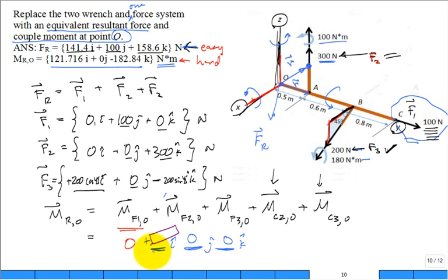Perpendicular distance of a half times the magnitude. A half a meter is that perpendicular distance, times the magnitude of 300 Newton. You get 150 Newton meter, positive. And really, we did a kind of scalar analysis to calculate that vector entity. All right. How about this one?